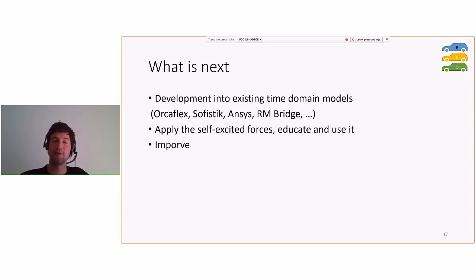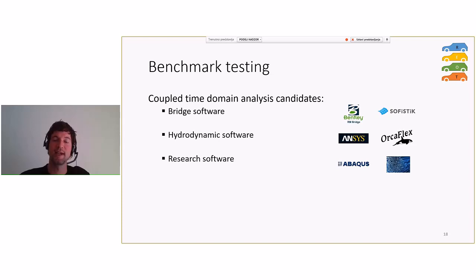And this was also a slide from my previous section. This is just a selection of a few software packages that have been used. In my research, I particularly investigated one, which I'll keep anonymous now, and we found that the flutter derivatives in time domain can be simulated successfully in time domain simulations. This software is used for bridge design, and it's not any special hydrodynamic software, and you don't need any special access to the code. You can just reuse the existing functionality of hydrodynamic linear wave radiation and simply introduce the right damping tables.